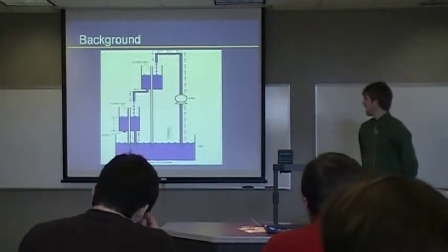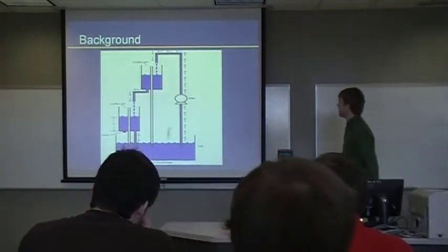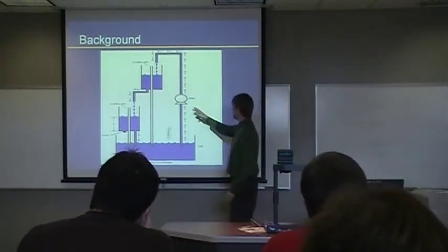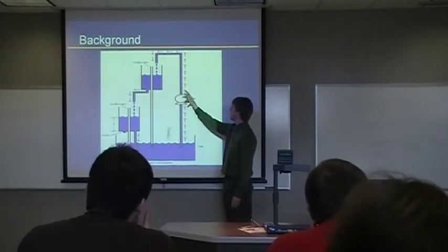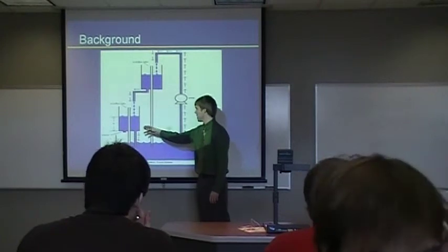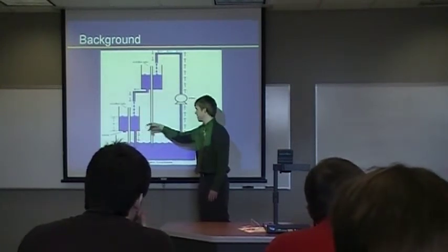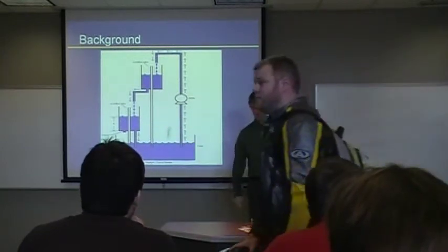Here's a brief schematic showing your pump, which is your manipulated variable, a reservoir tank that provides a flow to the storage tank, and this is what we're actually leveling. This is the CFT. There's a pressure sensor, which is directly correlated to the height of the fluid.